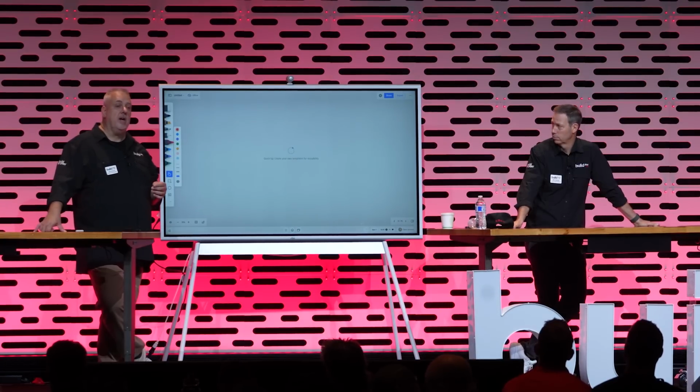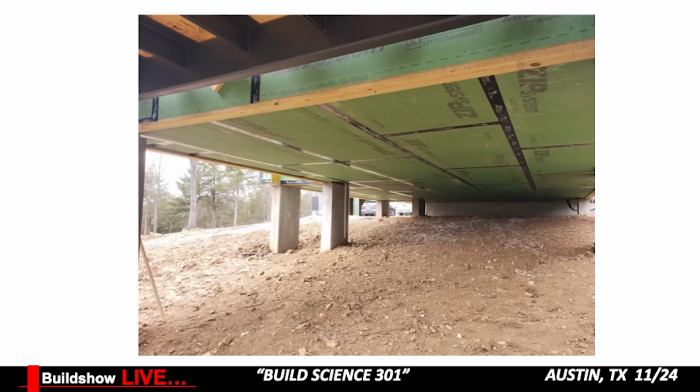Consequently, that's exactly what's on the wall. And there's a picture from the belly of the beast, right? ZIP R9. It works on the wall. It's a very effective air barrier there, very effective weather resistive barrier. What would cause me to question it to just turn the corner and use it as the same thing in the belly?